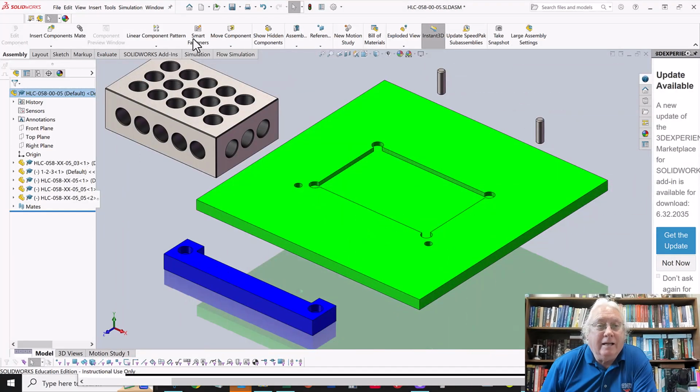So you should have already read the lecture slides and watched the first video, when I talked about the datum reference plane and locating the part, defining the part datum reference frame to get rid of all the 6 degrees of freedom using one scheme. And we're going to use a different scheme in this video that you're going to use when you do your assignment 5 drawing. So let's go to SolidWorks and take a look at the part.